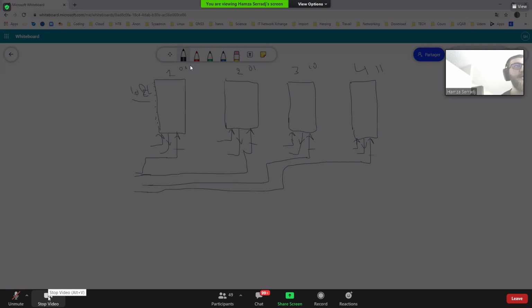And after, I will have the other 10 bits that describe the real address, right? So my address bus width here will be 12 in this case. I'm going to use 2 bits to describe which chip first. So this one is going to take the 10, but I'm going to need a multiplexer here.